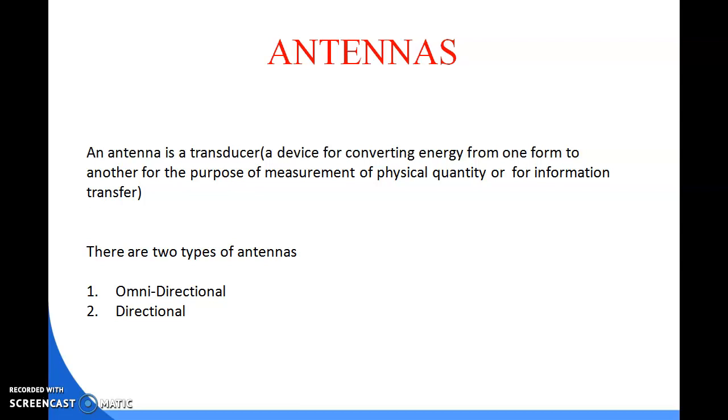An antenna's gain is expressed in dBi, and a directional antenna is capable of propagating the signal further than the omnidirectional type because it focuses the power in a single direction. Long distance transmission requires high power and a directive radiation pattern. Wireless LANs and WANs use omnidirectional antennas, and wireless MANs use antennas that are directive.